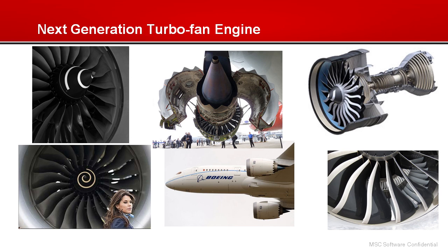These fan blades have been reshaped to move the air more efficiently with fewer blades, and some of these blades are made of carbon fiber to save weight. And in order to keep that fan turning, a small percentage of the incoming air instead flows into the core, where it passes through two compressors. It mixes with fuel and ignites in a combustion chamber. That combustion powers the turbines that drive the fan up front. It's awesome technology.